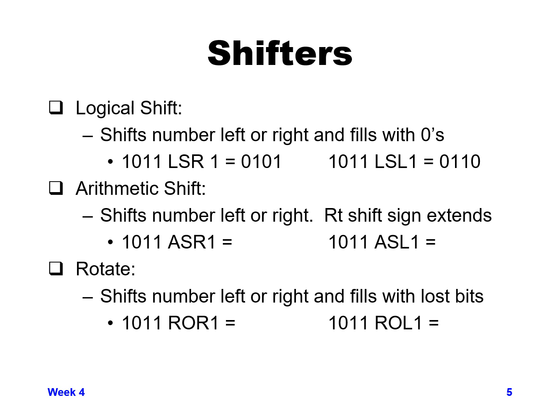For an arithmetic shift, we do the same type of shifting, but the number that we fill in will be a little bit different than the logical shift. So we'll shift the number left or right. What happens when we shift right is we do a sign extension. So whatever the leftmost bit currently is, we'll keep that value there. So for a 1, 0, 1, 1, when we shift to the right, we keep the leftmost bit value 1, and then we shift the bits to the right, and we lose the rightmost bit.